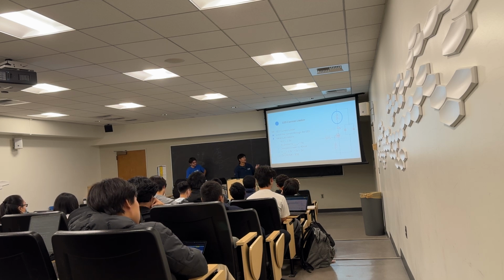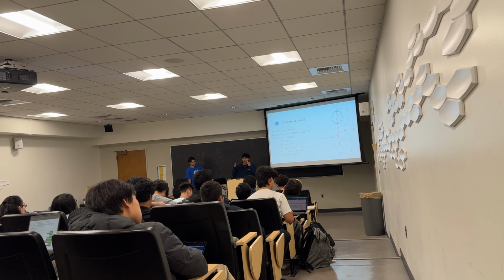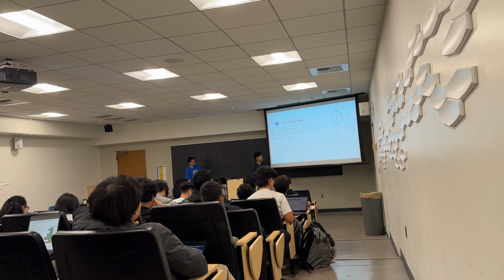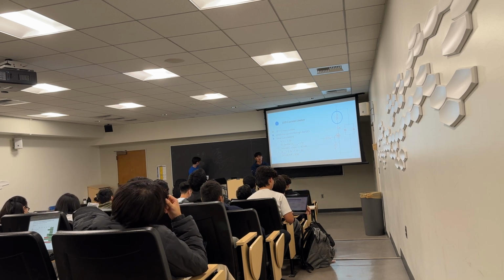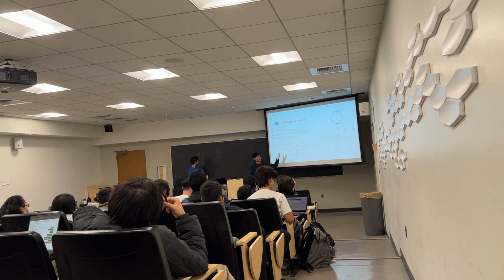And our ideal IR emitter forward voltage, it's called forward voltage because an LED is a light emitting diode, and diodes only want current to flow in one direction, so that's why we call it forward. But ideally, we want this voltage drop to be 1.3 volts, right? So if the voltage drop across this IR emitter is 1.3 volts, where does the extra 2 volts come from, right? So we have to make sure that it drops an additional 2 volts across our resistor.